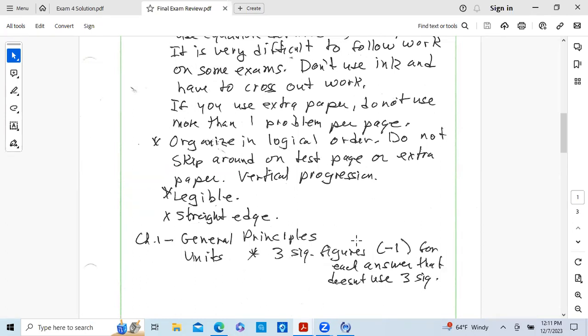We're taking beams and we got loads of 10,000, 8,000, 5,500, and you give me an answer in a support of 425.32. You're telling me something that's not true. Okay. We're probably measuring out to the nearest 10 pounds, 100 pounds, and you're telling me the answer's in hundredths of a pound. That's not right.